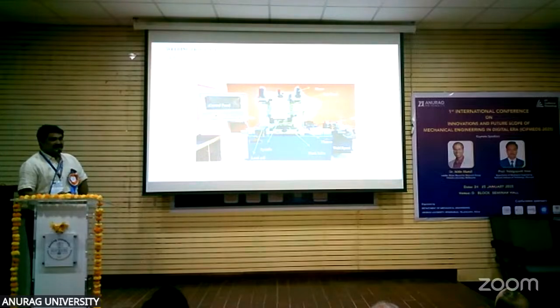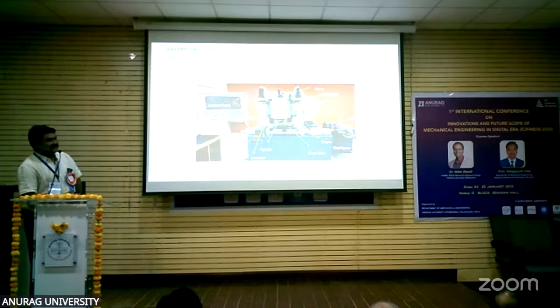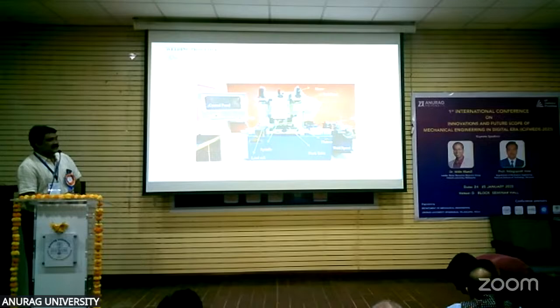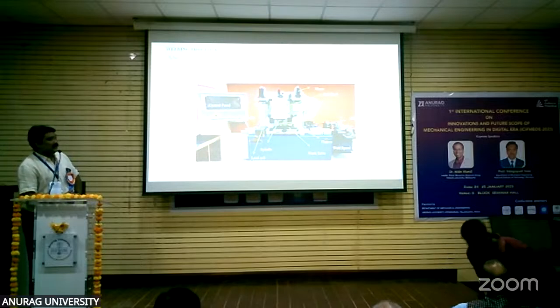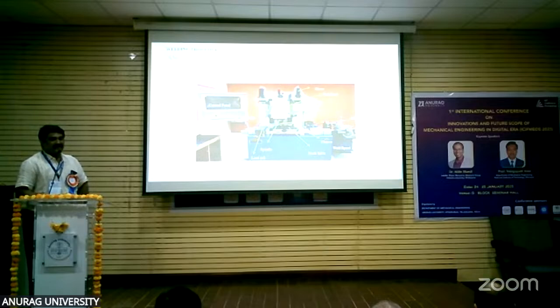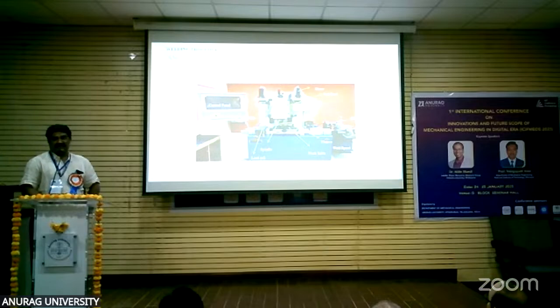And this is the experimental setup, and these are the parameters considered. The rotational speeds are 900, 1350, and 1800, and the weld speeds are 16, 26, and 36 mm per minute. For the combination of experiments, we take 900 speed with 16, 26, and 36 weld speed.